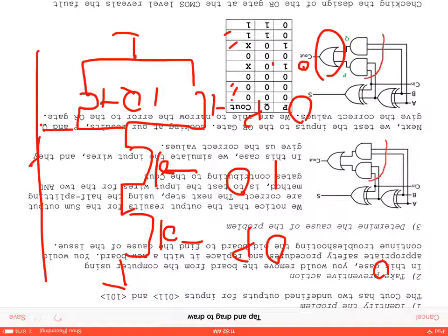So what's the output path supposed to be through? NMOS. Which NMOS? The Q. The Q, right? So we have a PMOS off, and we have Q. Its path is supposed to go through here, right? From 0 to the output. But we're getting an indeterminate value. So something's up with this transistor here.